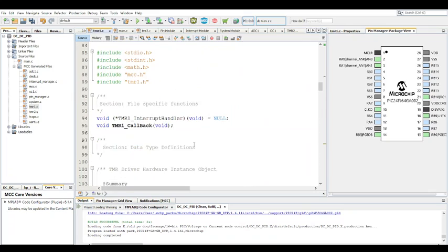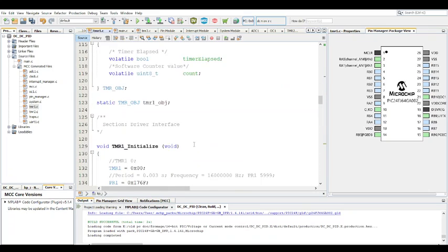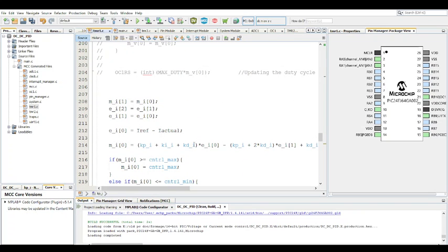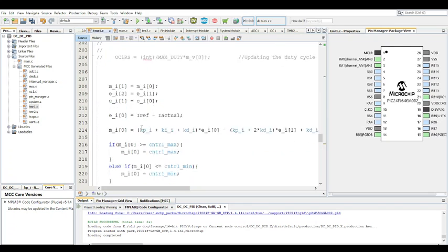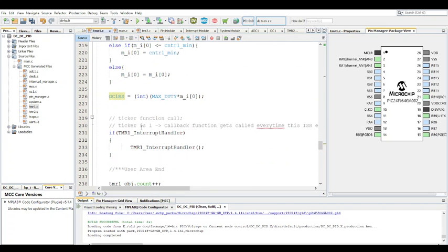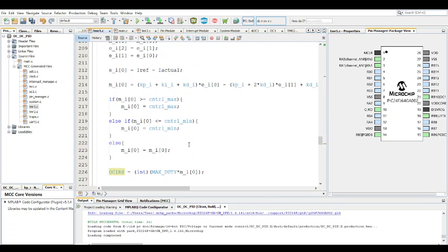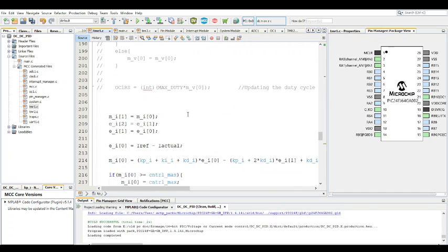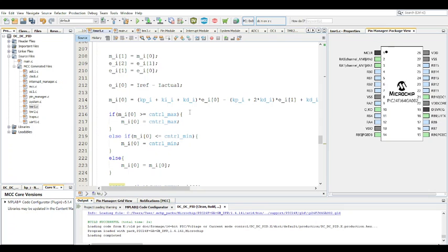Obviously you can find the code and modify it as you wish. I will not be held responsible if you modify it out of control and maybe it does something not so nice to your system, at your own risk, obviously. But the major purpose of this was essentially just to show you this is how you go about coding constant voltage to constant current control for whatever applications you need. Just in this particular scenario for these tuning rules, I'm specifically talking about DC-DC converters, specifically a boost in this case.